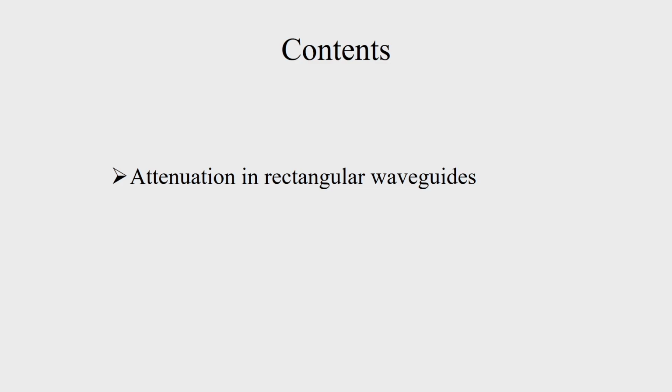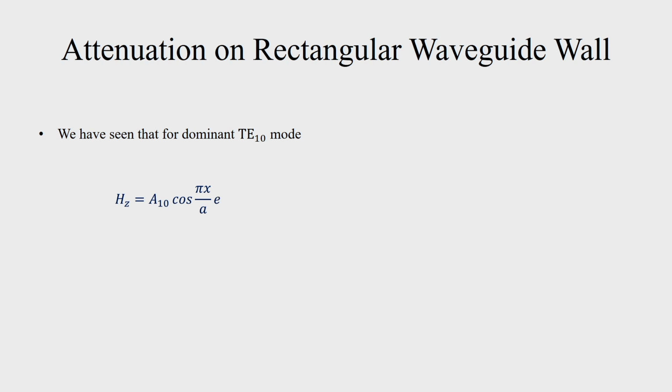We now cover these two topics, attenuation in rectangular waveguides and attenuation in circular waveguides. We start with formulating the attenuation in rectangular waveguides. We will restrict our discussion to the dominant TE10 mode only, and for the TE10 mode we have seen the longitudinal field